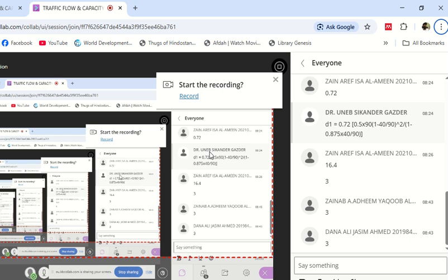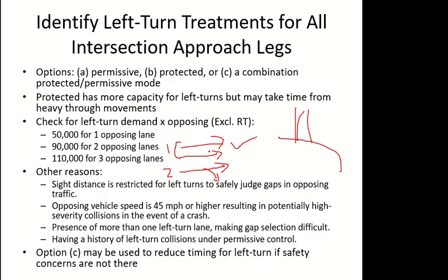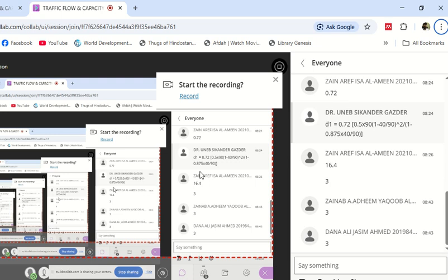You understood the difference between number of lanes and number of lane groups. So you can pack up multiple lanes in one group if their capacity and their movements are the same. And yes, capacity will be the same if their movements are the same. I have two lanes here with the same movement, and I have another lane which has one extra movement. So these two will have the same capacity, so I can take the capacity of 1 multiplied by 2. This will make one lane group. For this one I have to calculate a separate value of capacity. Got it? Any questions? Any problems? Any confusion?